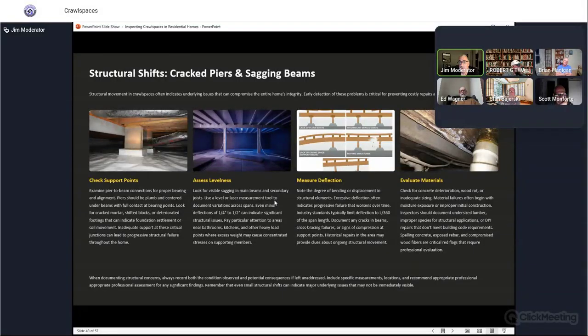And I've seen no modern 2x6, 2x8, nothing, sistering it. I just call it out all the time. I just call it out for examination of the framing as a whole. Even though the house has been there for a couple hundred years, it's good to protect yourself.